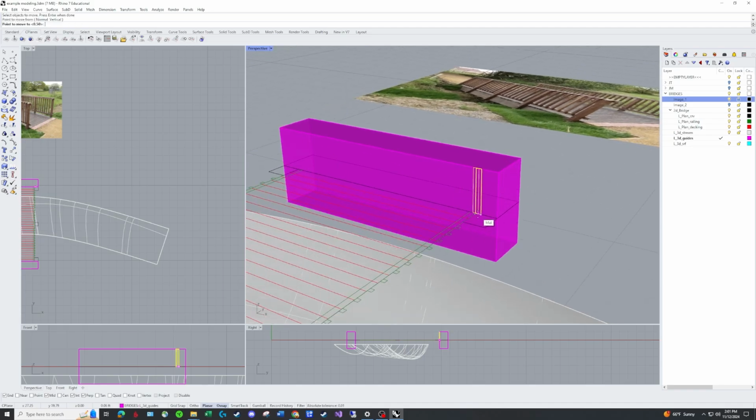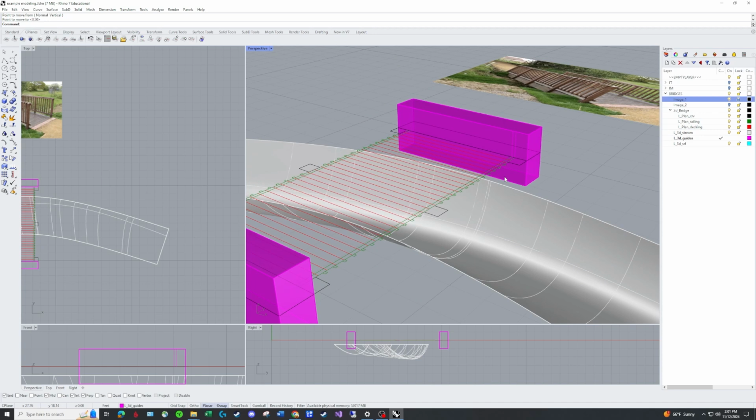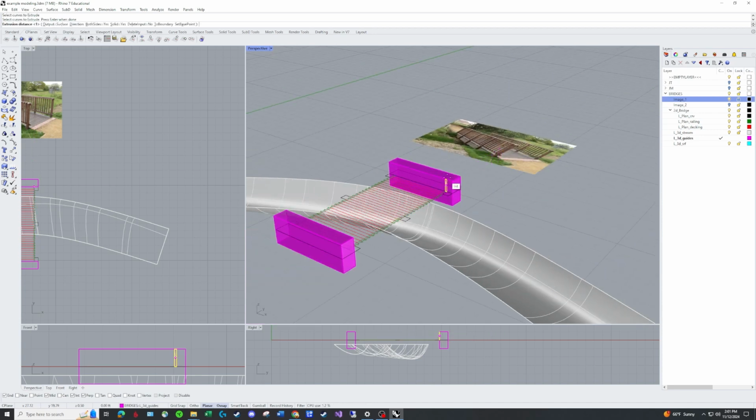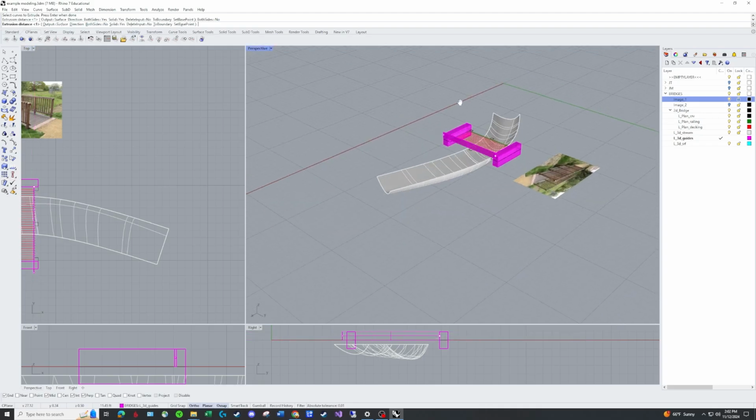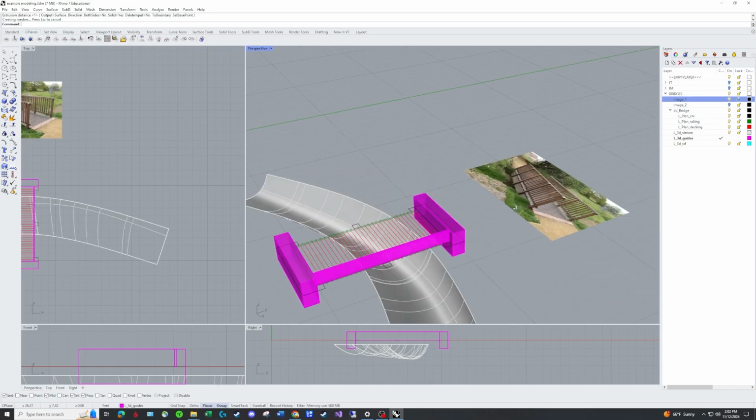And so I'll put this on the edge because it does represent the edge of the decking, the edge of the bridge. So extrude curve, so we'll come all the way, and I don't want this one both sides, so I'll turn this off. And just to make sure I get this right, I'm going to snap to a corner, so I want it to be right there.